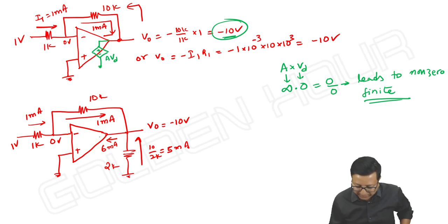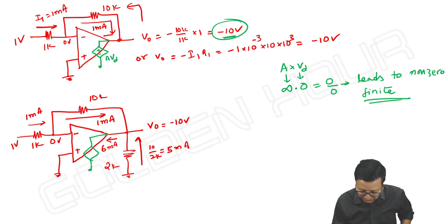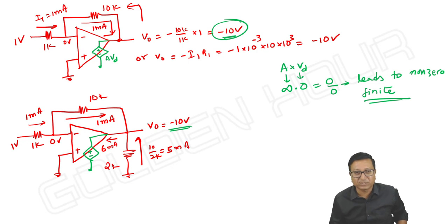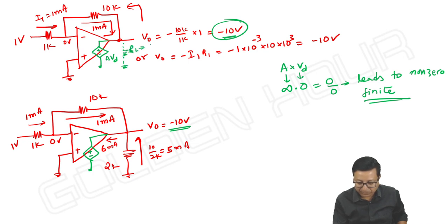Okay, and here also the same source we can show. The voltage source value does not change. And here a voltage source without RL; here RL is infinity. Here RL is equal to some 2K. RL is infinity, that's why IL is 0.